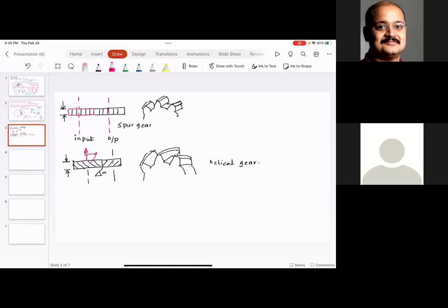Because of the gear geometry, the helical gear will continue to add thrust to the clutch plate, which would ensure that the clutch plate is in positive contact from the input side to the output side. So helical gears are used when you need that constant thrust to be present. Spur gears are commonly used for power transmission, but they do not give you the thrust.